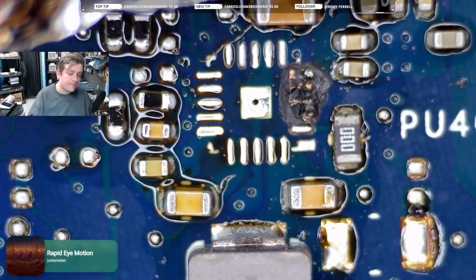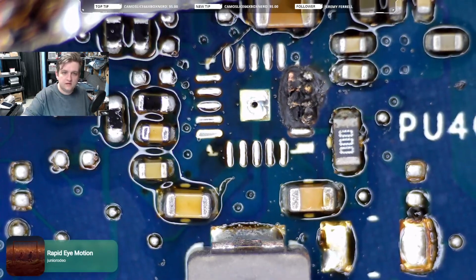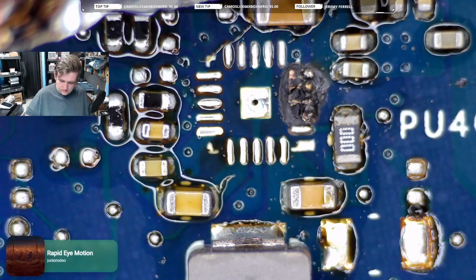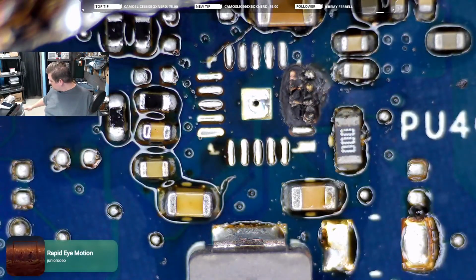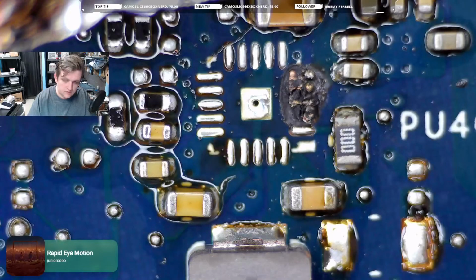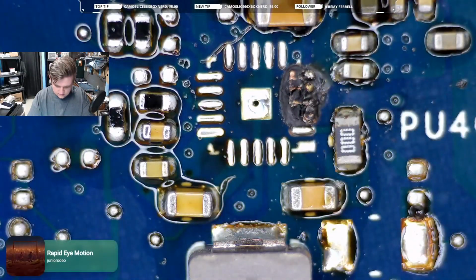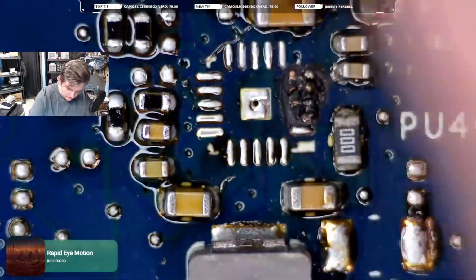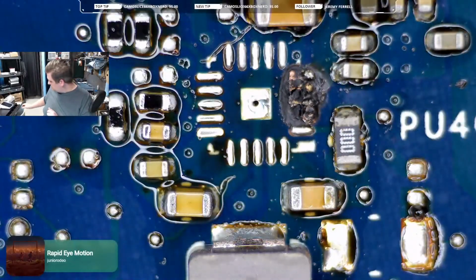So that chip, I was trying to take it off, but the leads were keeping the chip in place. It was not wanting to come up. So instead of pulling the chip upwards, ripping those leads, and doing trace work for a QFN chip that is like a quarter the size of your thumbnail, I pulled to the side away from it. So not up, but away. And in doing so, knocked a couple of components. It's fine. I have the picture of everything before I took the chip off. Surrounding area, always good to do so. And I was able to move that stuff over. So I think we're good.